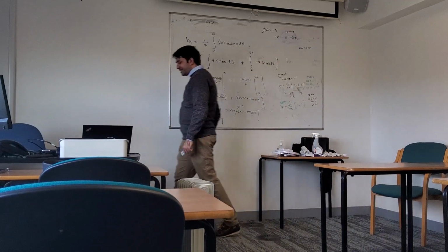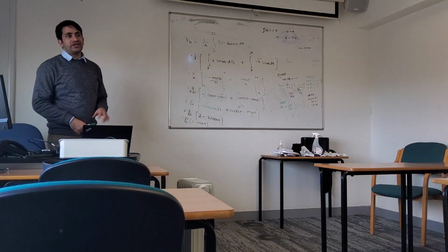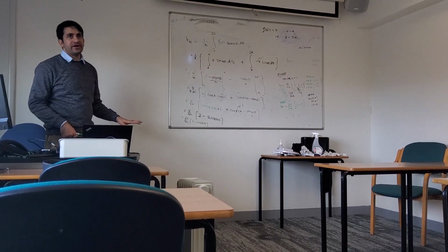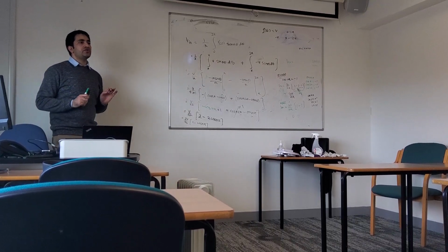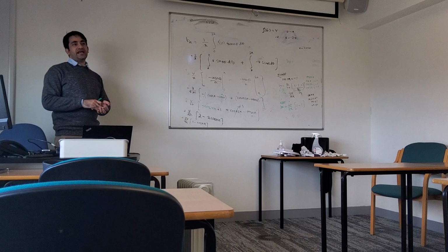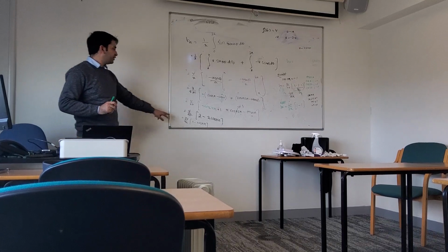And finally, you will see that you have Bn 0. So it means that for this specific waveform, the square wave, you only have value for Bn for odd n, right? For even n, Bn is 0, your a0 is 0, your an is 0. So it means that we have found our Bn.